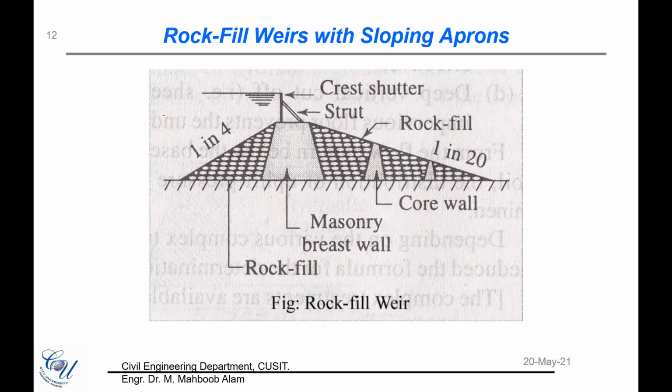So let's say if you follow the line here, if water is entering in this direction, then we provide a structure inside this barrage or weir body so that this line is discontinuous. It is not a continuous line which is showing up somewhere here.